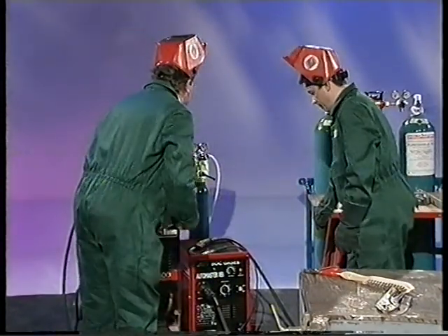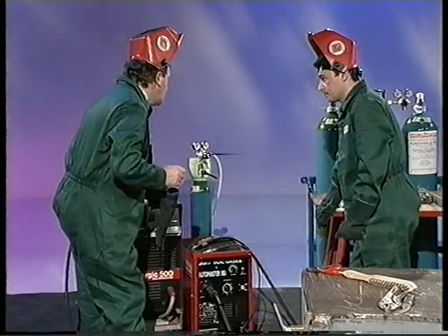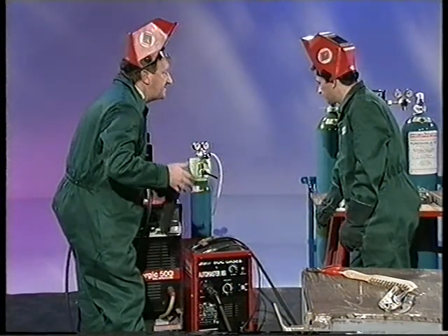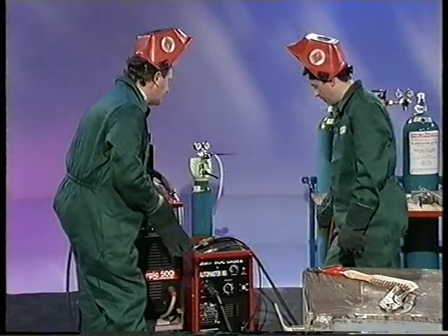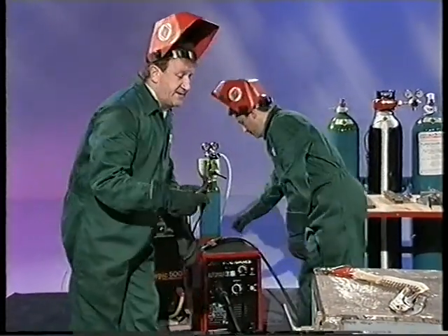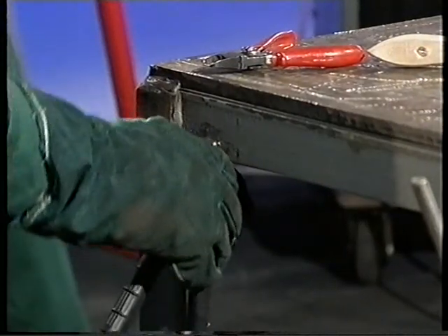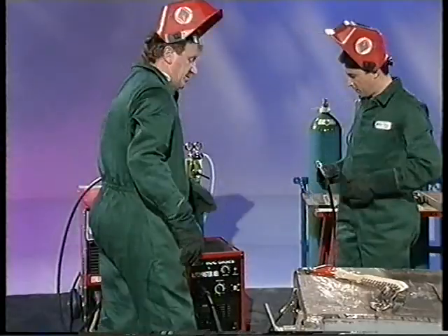The gas we set on, but in this case, because we're going to be doing quite low amperage work, we set around 15 litres per minute. There's no need to have quite as much gas flow as on the higher amperage work. Okay then, we need to connect the earth lead to the bench to complete the electrical circuit. Power it up. Turn the machine on, thank you.